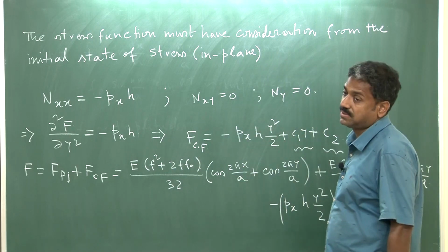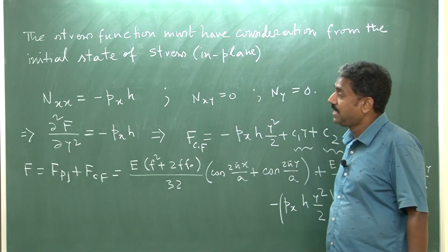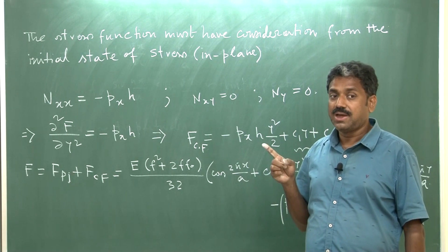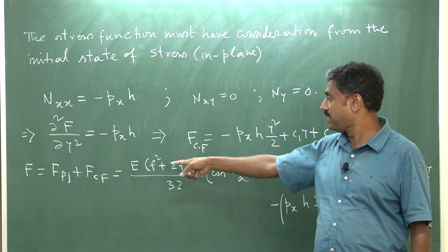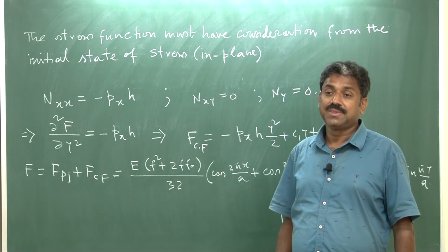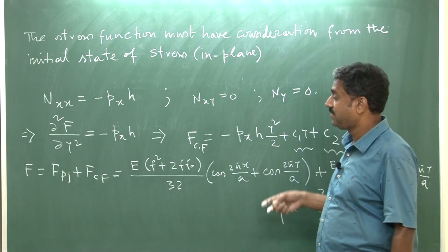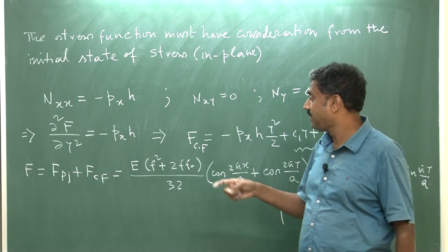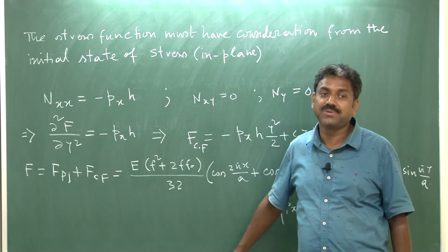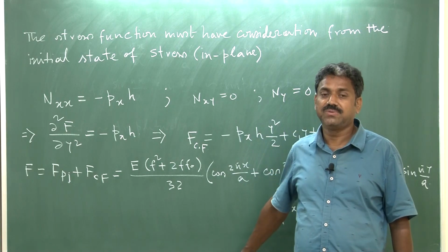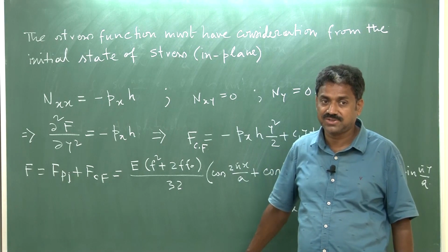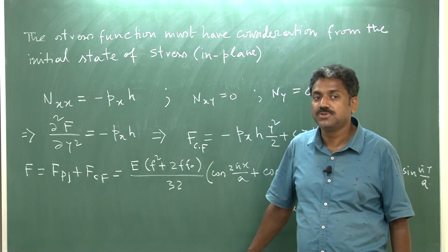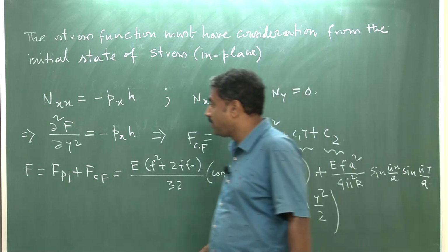So, this is the stress function, right. Now you see I have the displacement profile w, but f and f0 are not known, these are unknown, right. But we got a functional expression of F in terms of w and w0, right. So, how to determine f0? Because f0 is what? The imperfection amplitude. If you do measurement, then you should know the imperfection amplitude, right. But what you do not know is f, because f is the amplitude of displacement, right. So, how will you do that?